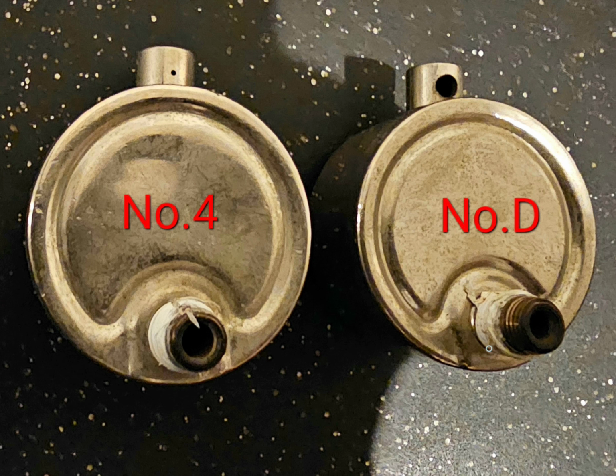But usually, the way cast iron radiators are constructed, once they heat up, as long as they've got steam inside of the system, it's consistent steam going into the service valve, into the radiator, and all the air has been vented out, that radiator probably is not going to cool down at all until you shut that boiler down. But I'll explain that more in another video.